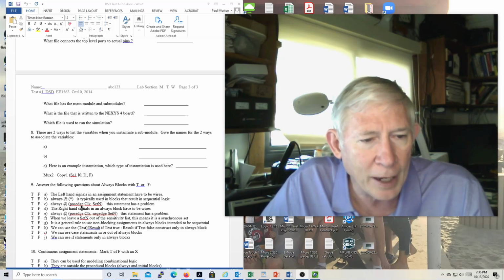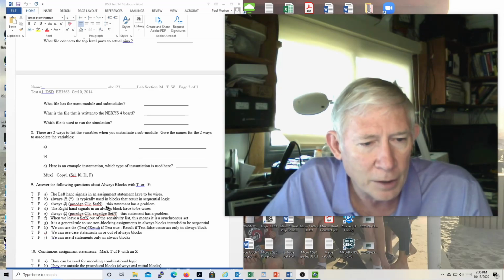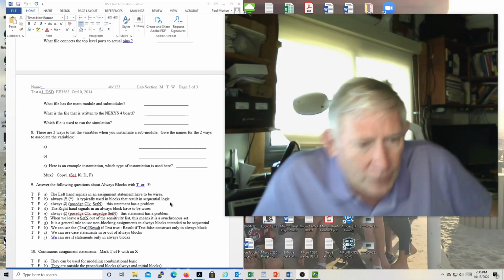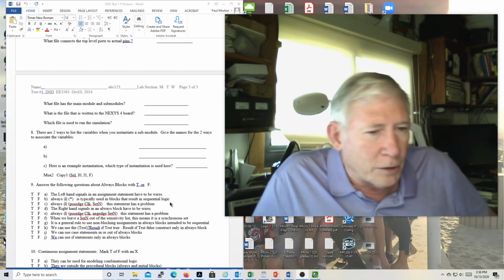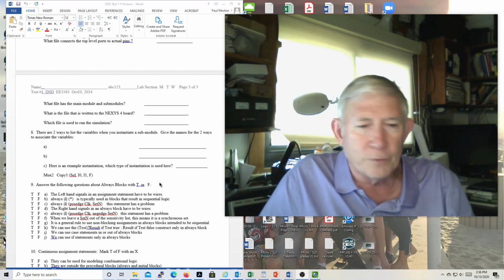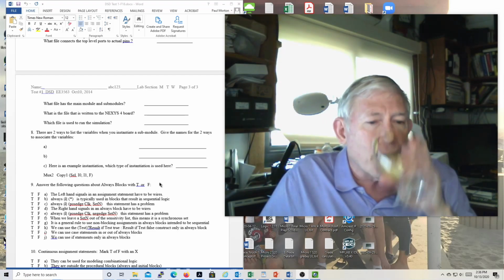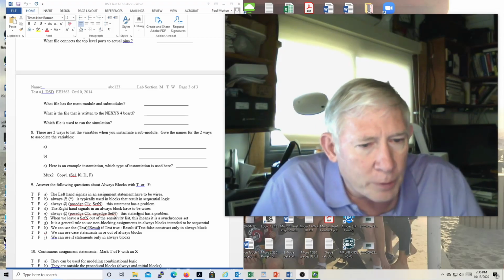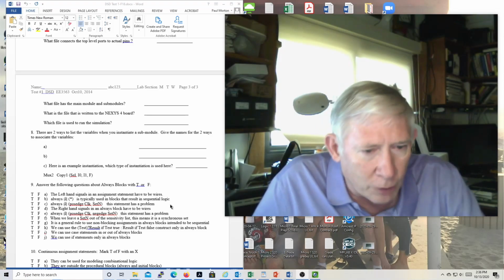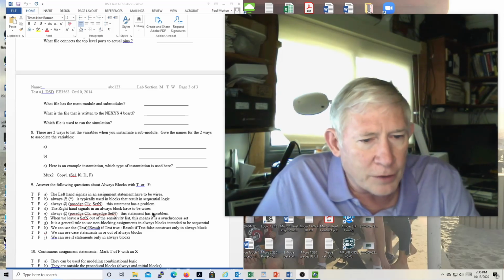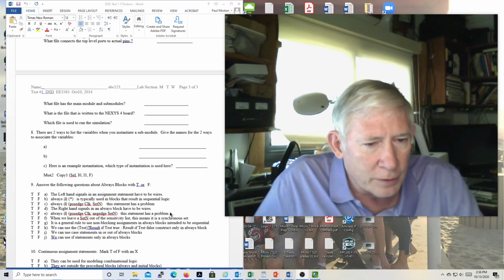The always at posedge clock, comma, set_n. This statement has a problem. Yeah, your set_n must also be an edge signal, and so you have to specify that. I know at least one student said they had problems using the push button, even calling it an edge. I'm a little confused about that, but it should have been legal, so I don't know what was going on there. The right-hand signals in an always block have to be wires. No, they can be wires or registers. The always at posedge clock negedge set_n. This statement has a problem. No, that statement's fine. It should be good.